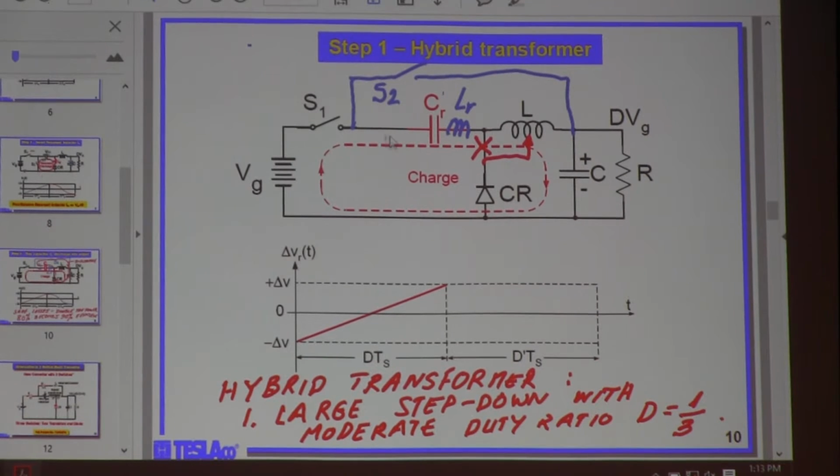What about here? If I turn the switch on, is this voltage going to go to 12 volts suddenly? No way. Because why? There is a capacitor divider between this way, and if this ratio of capacitance is 10-to-1, even if this is constantly turned on, of course this is down at the ground, the output will always show 1 volt. Doesn't matter if it's short, permanent or not.